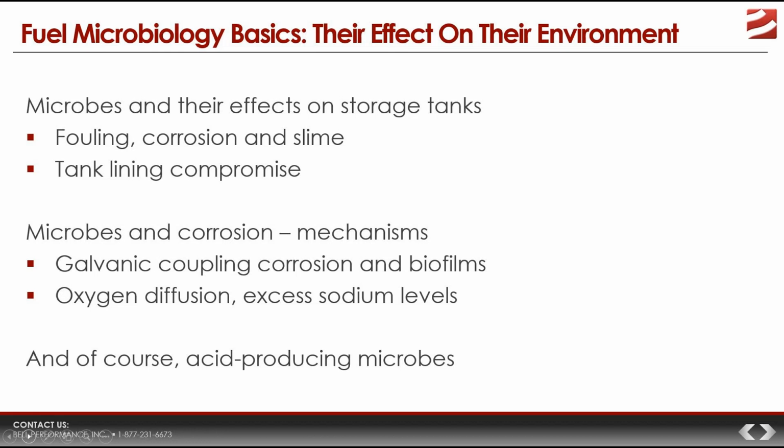They can just colonize the surface of fiberglass. They send out their little hyphae, which penetrate into the fiberglass. They start consuming the resin. They start deplasticizing the fiberglass, and then you get a major compromising of fiberglass tank surfaces.